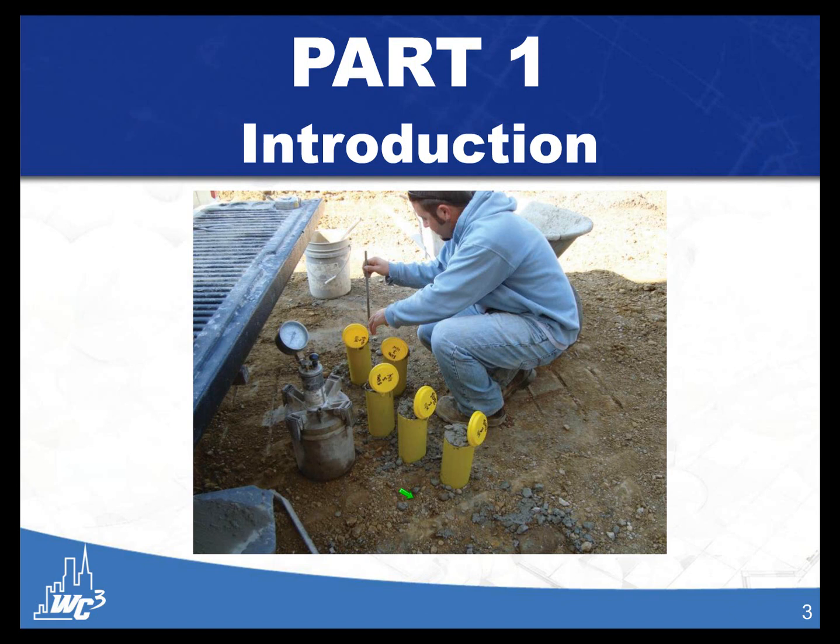So there's a lot that goes into just sampling concrete, and that's just one tiny item of all the different types of materials and special inspections that are discussed in Chapter 17. But there's a lot that goes into just this one item. And I want to highlight that because it's not appropriate when we get into a statement of special inspections to just say, provide special inspections of concrete. We really need to be breaking it down, describing the extent and what we're doing. And so we'll discuss that a little further.